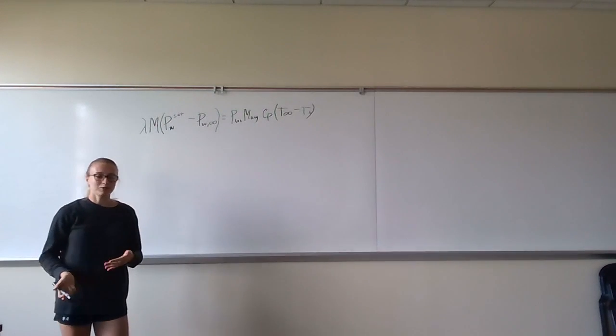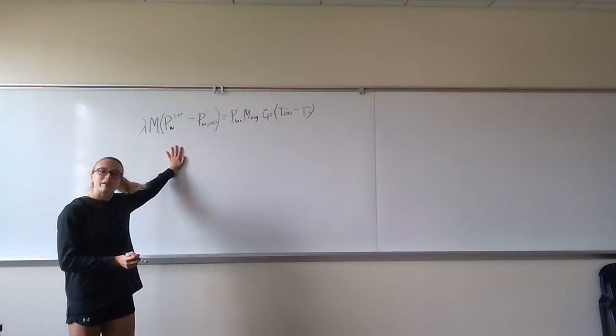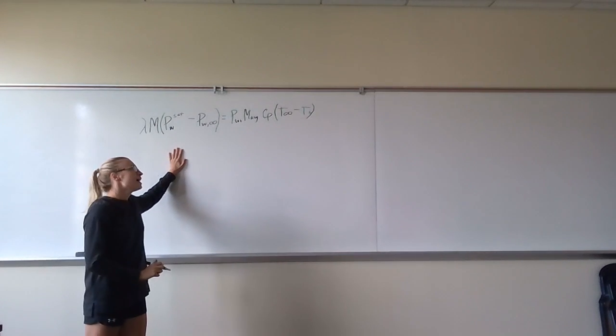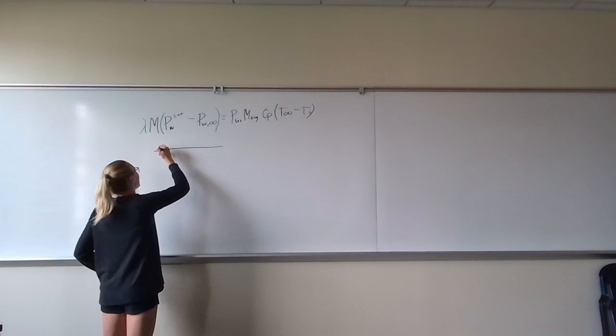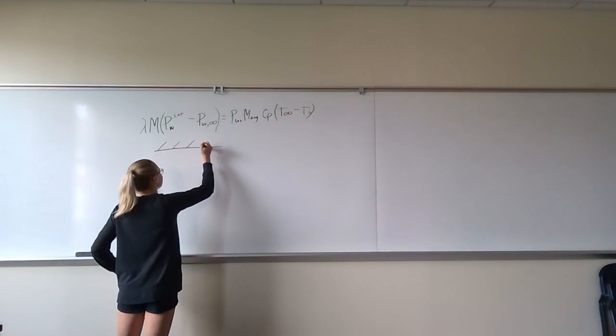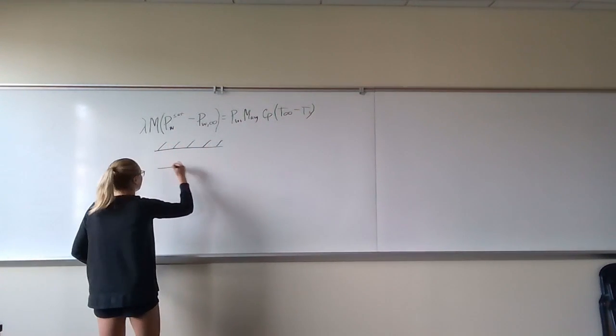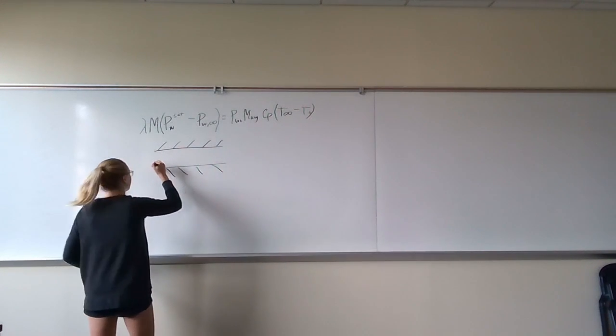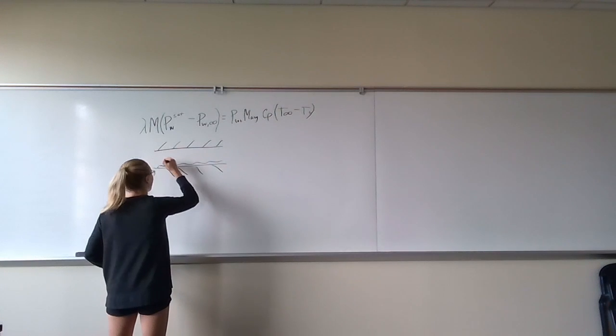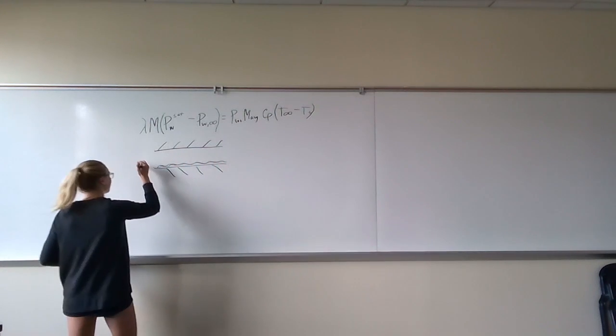So this is for the wet bulb thermometer temperature, and when establishing the adiabatic saturation temperature equation, we can consider an infinitely long pipe that is perfectly insulated. Water is continuously flowed through the pipe, and the water remains the same temperature throughout.